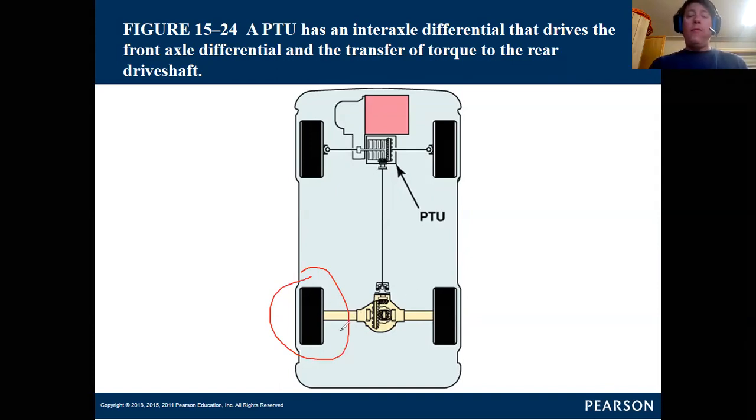So what the manufacturer can do, by biasing power flow between the right and left wheels, is use a brake component to clamp down on that tire's brake and stop it, which then forces power to move to the other side that does have traction. And happy face, you get to start moving down the road.